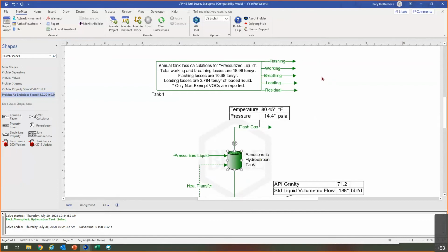If you're looking at actual volume instead of standard, standard is nearly always used because it's consistent. So if you're given a volumetric flow, it's almost always in standard volumetric flow. And again, pressure will not matter for that. If you were looking at actual volumetric flow, that would make a slight difference. The pressure change here is so small, it wouldn't be much regardless, but the physical properties and the compositions won't be affected by doing that.